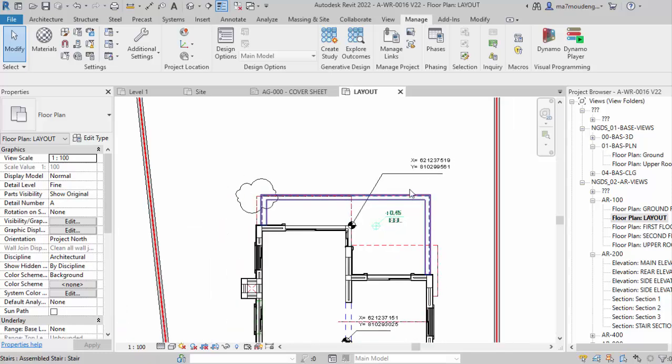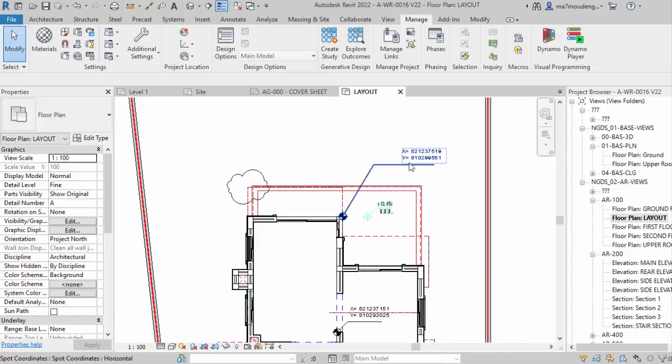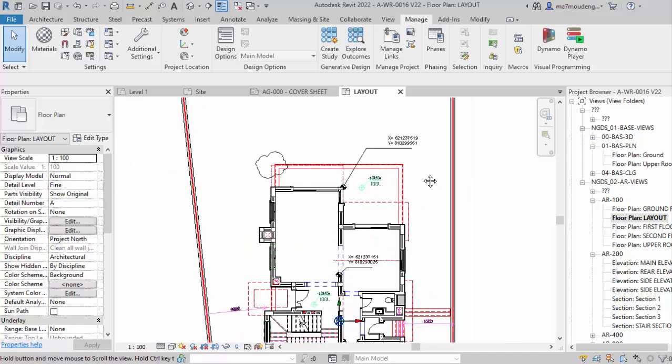That means it doesn't matter how many positions I have for the same building, as long as I'm using the shared site file, it's easy. If they told you, please print all the drawings again, but according to the new positions, and you don't want to duplicate the Revit file and keep changing everything, because that doesn't make any sense.